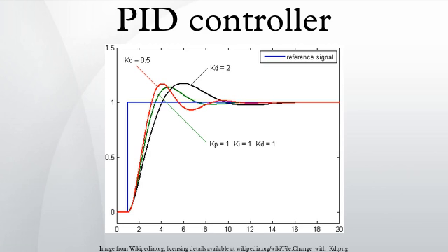As low-pass filtering and derivative control can cancel each other out, the amount of filtering is limited. So low-noise instrumentation can be important. A nonlinear median filter may be used, which improves the filtering efficiency and practical performance. In some cases, the differential band can be turned off with little loss of control. This is equivalent to using the PID controller as a PI controller.